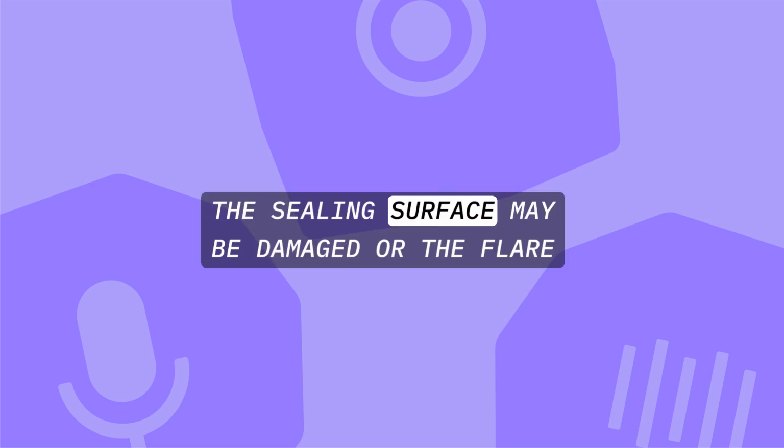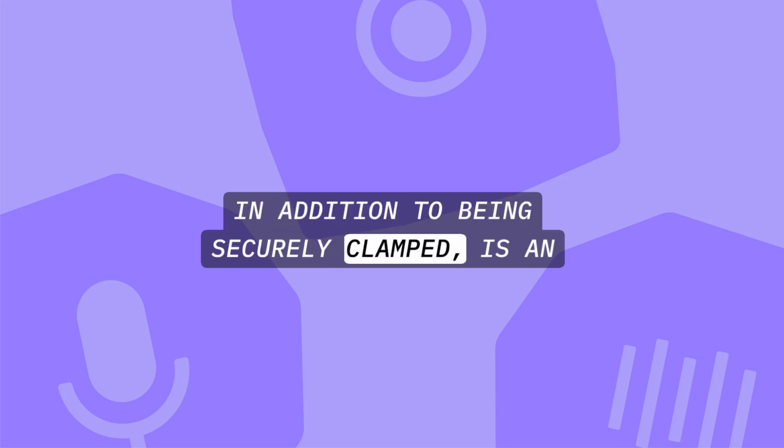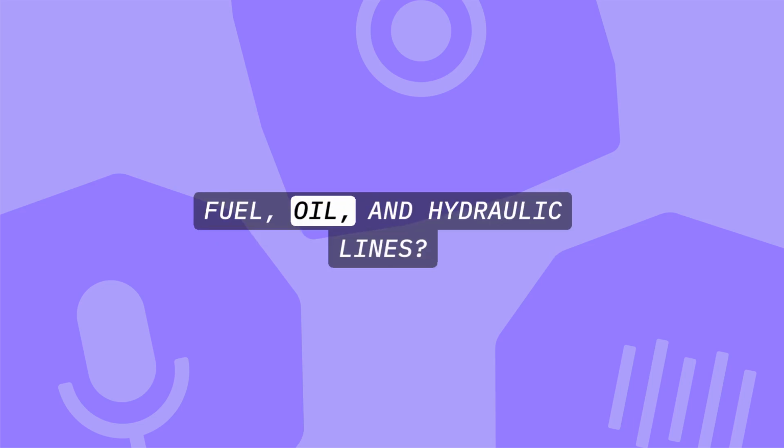The sealing surface may be damaged or the flare cut off. In addition to being securely clamped, what is an additional requirement for installing metal fuel, oil, and hydraulic lines? The lines must be electrically bonded to the structure.